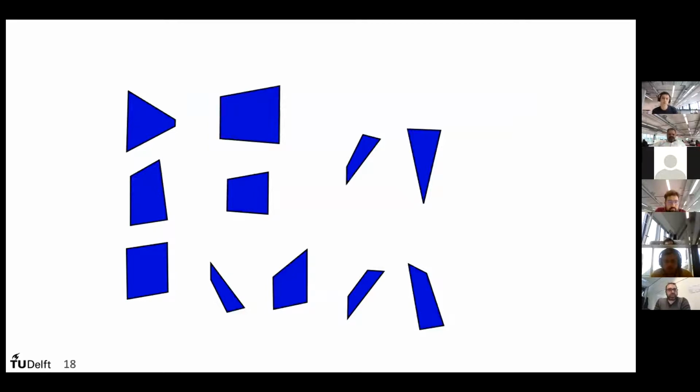And of course, this is interesting and good, but as I mentioned before, when there is shading, so when there is non-uniformity, we have different current generation. And in this case, different pieces would have a different active area, and they would also lead to a different type of non-uniformity that is not related to the shade, but to the amount of silicon area that you have in the different pieces. So an optimization is needed here.